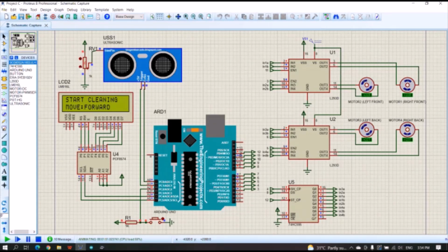If it's facing an obstacle, then it will stop and turn to another direction, and when it finishes turning, it will stop and scan again. And if there is an obstacle, it will turn the other side. So as long as after it stops and scans, there is no obstacle in front of it, okay, scan, there is no obstacle, so it will continue to move forward.